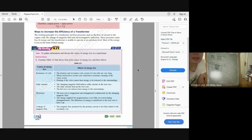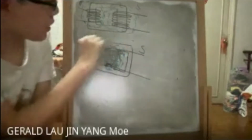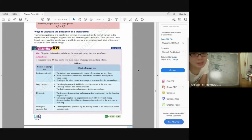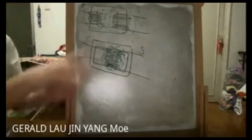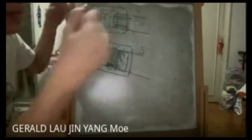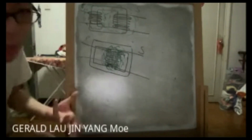Okay, the third factor is hysteresis. What does it mean, hysteresis? The iron core is magnetized and demagnetized continuously by the changing magnetic field. That means this iron core is suddenly magnetized, demagnetized, magnetized, demagnetized. So energy supplied for magnetization is not fully recovered during demagnetization. The difference in energy is transferred to the iron core to heat it up. So you see, all of these factors cause the iron core to heat up and lose energy through heat energy. So it's not good.